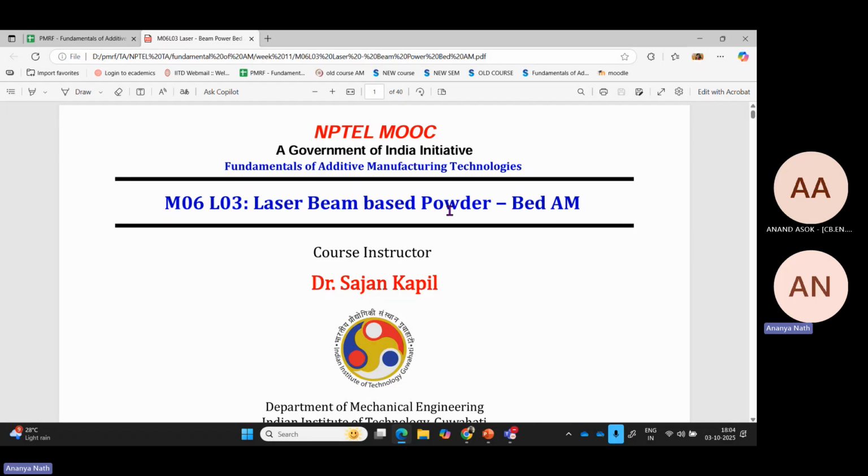As an energy source, I have mentioned laser, but electron beams can also be used. So EB PBF is also there. PBF, powder bed fusion, can be again of two types, PBF-EB, electron beam, or PBF-LB, laser beam. In this class we will mainly focus on PBF-LB, that is powder bed fusion with laser beam.